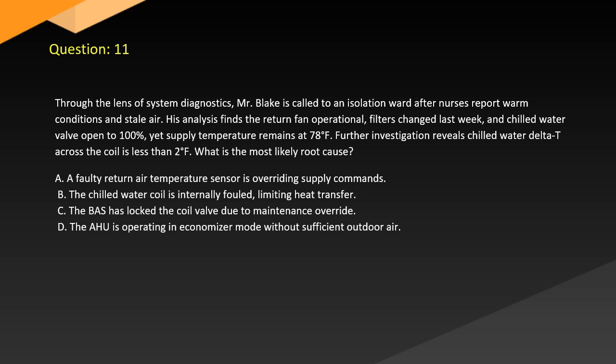Question 11. Through the lens of system diagnostics, Mr. Blake is called to an isolation ward after nurses report warm conditions and stale air. His analysis finds the return fan operational, filter changed last week, and chilled water valve open to 100%, yet supply temperature remains at 78 degrees. Further investigation reveals chilled water delta T across the coil is less than 2 degrees. What is the most likely root cause?